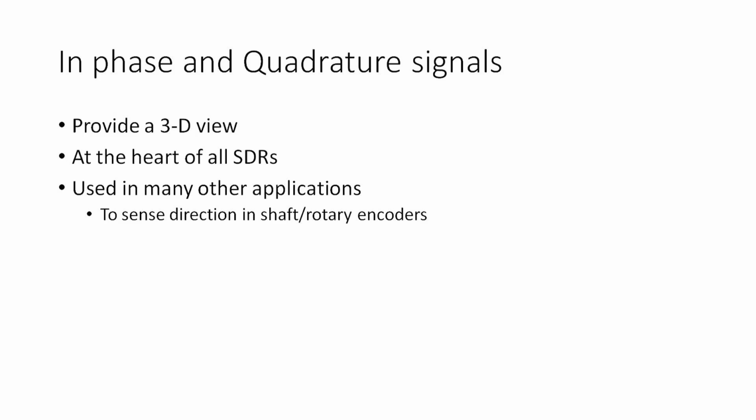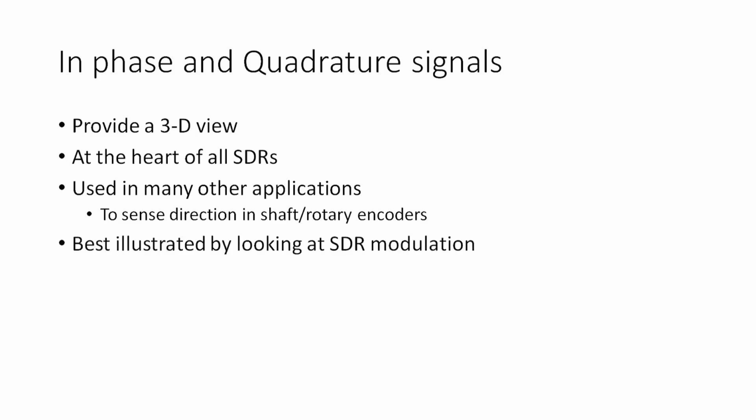A common way it's used is, you know, the little rotary encoders you've got on all your transceivers these days that just go round and round and round in place of volume controls and multi-way switches. Well, they work by having a common pin and an A and a B pin. And when you turn it clockwise, the A pin pulses before the B pin. When you turn it anti-clockwise, the B pin pulses before the A pin. And they're in quadrature, so you can tell which way it's going by looking at these pulses. And it's exactly what we're doing with I and Q signals.